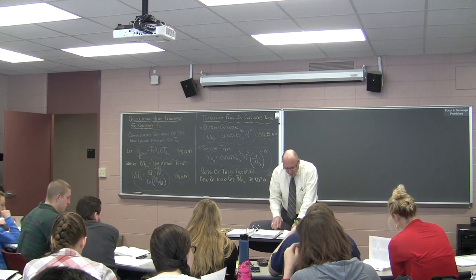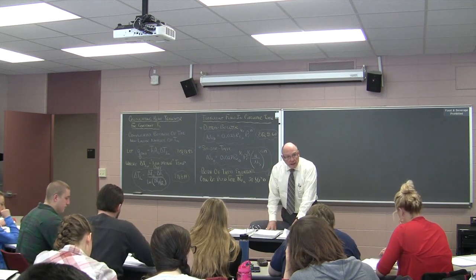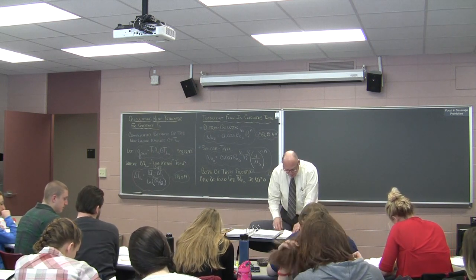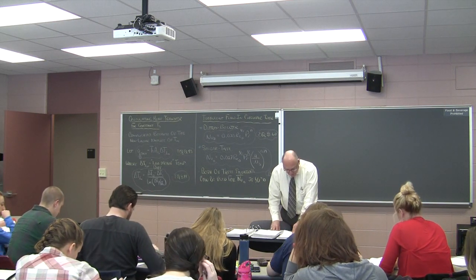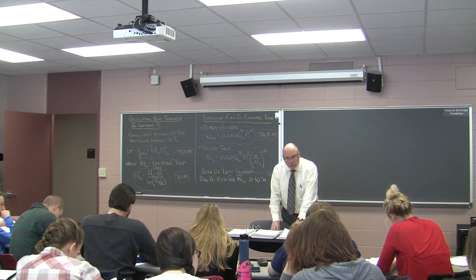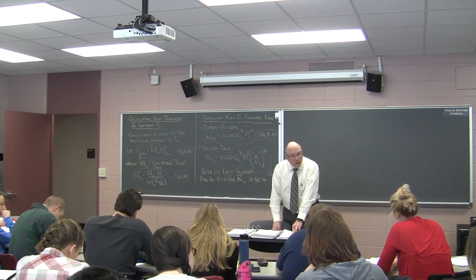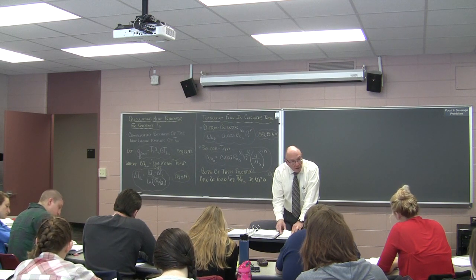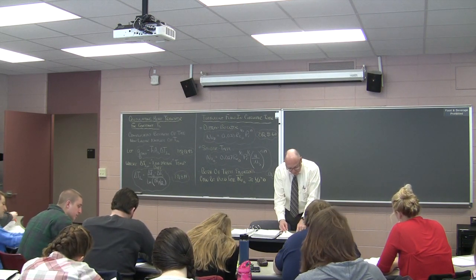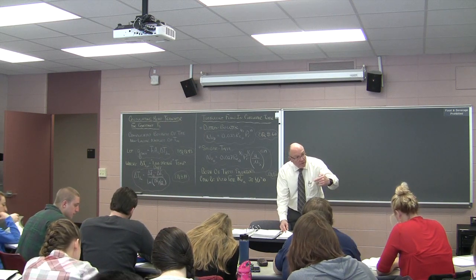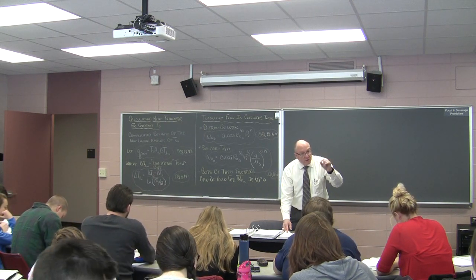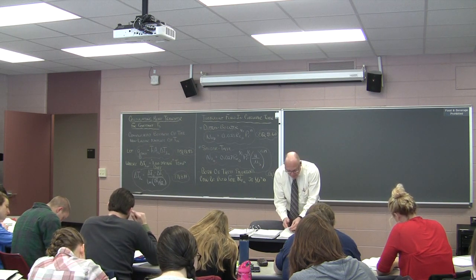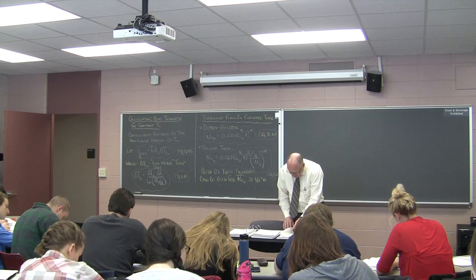That is the laminar flow hydrodynamic entry length. Should be highlighted in yellow. You should be able to go to it right like that. Look down below it, equation 8.4. It is the entry length for the hydrodynamic entry length in turbulent flow. And remember, we discussed it for the purposes of this book. Next sentence down, we're just going to assume that L over D is greater than 10. Okay? All right, that's the hydrodynamic entry length.